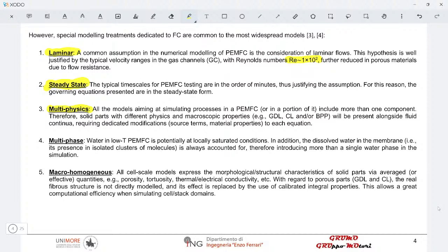And this will involve basically all the transport phenomena. If you are familiar with heat transfer problems, basically all fuel cell models are conjugate heat transfer models, because we will have the heat transfer between a fluid domain and a solid domain. And these have to be tightly coupled one to the other. So we will have a two-way coupling. This relates to heat transfer, but we will see that we will relate also charge transport. Okay.